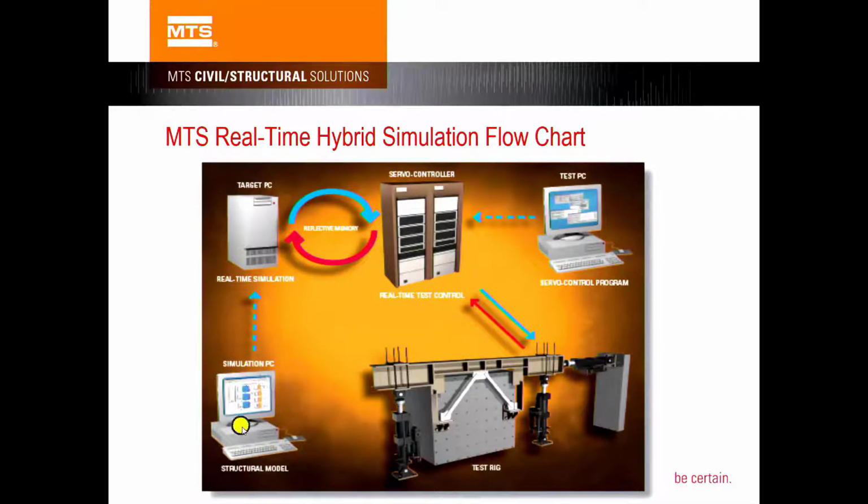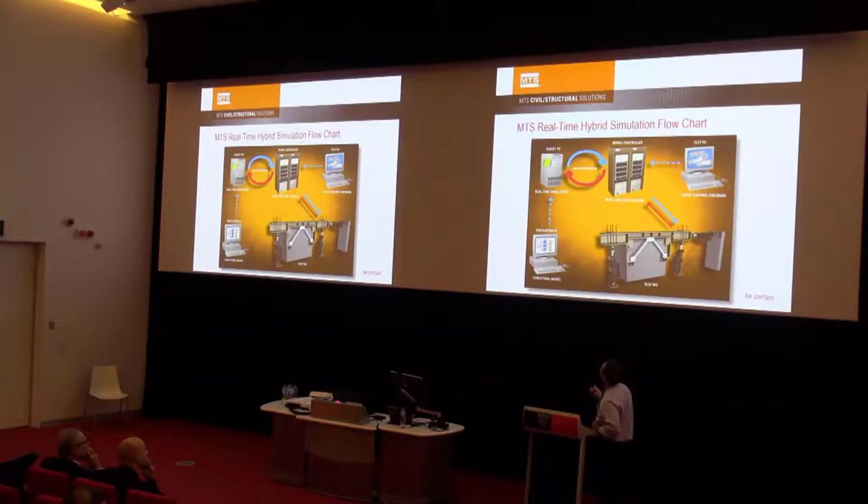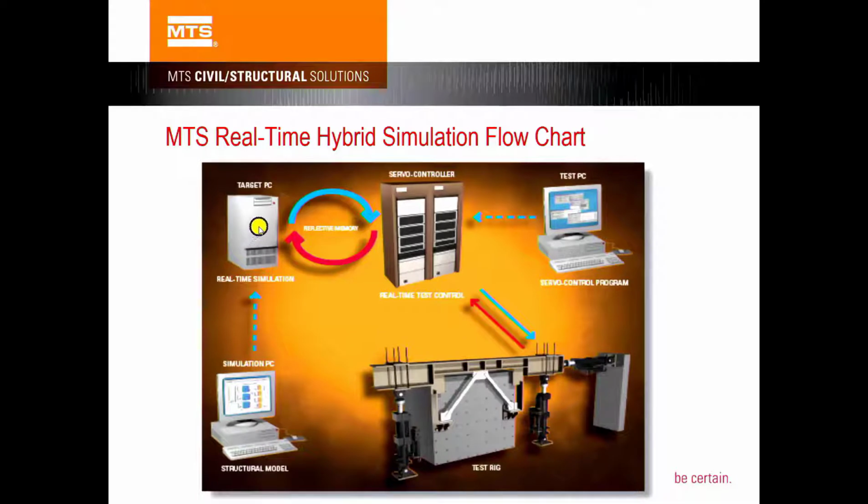The model is converted to C++ code and runs on this target PC. The target PC has a very simple operating system, not like Windows, so it is very efficient with not a lot of overhead, and the model can be solved really fast. Then there's a chance you can catch the real time.